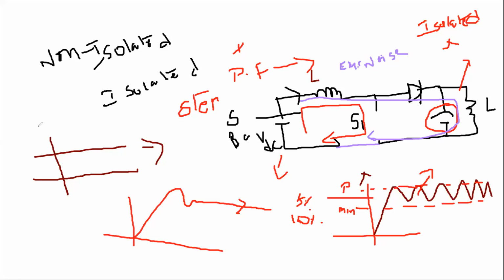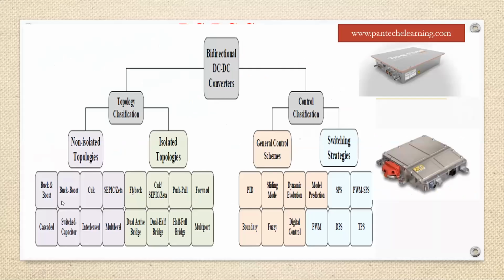So what are the types of converter topologies we have, and the specification of those DC-DC converter topologies, you can see here. Here we have buck and boost, buck-boost, Cuk converter, SEPIC and Zeta, flyback converter, right? If you observe here, in the buck and buck-boost converters, the power factor may be near 0.62 or less than 0.7. Why are we focusing on the Cuk type of converter? The buck-boost nature is also in the Cuk converter.